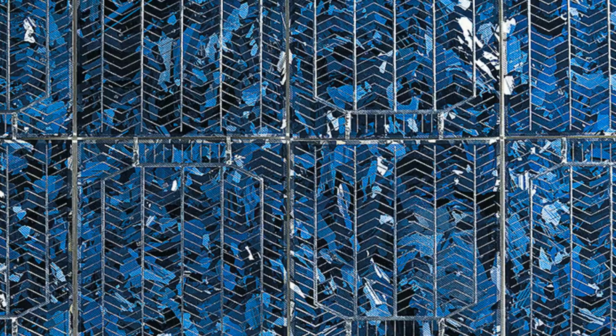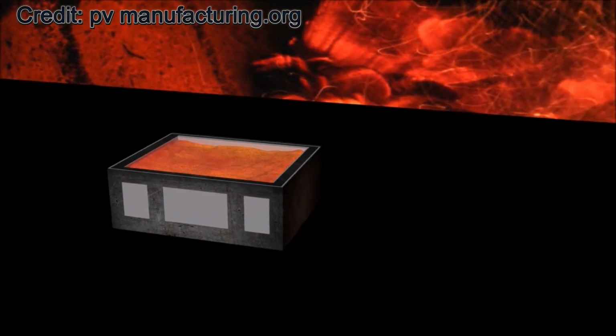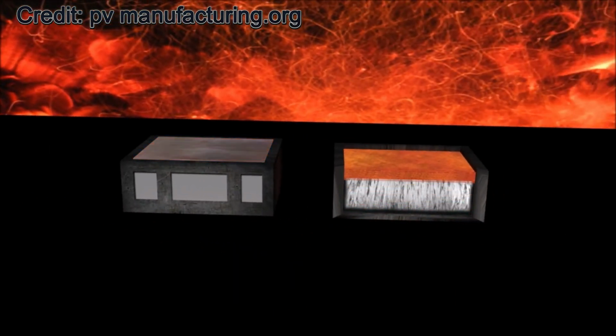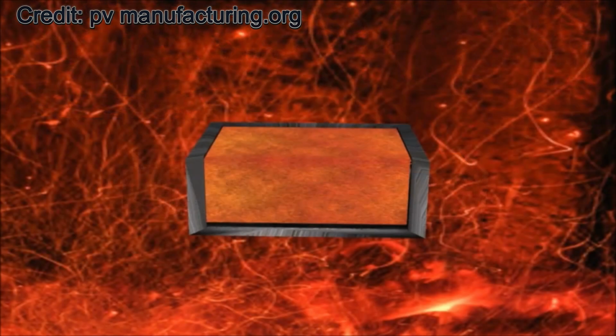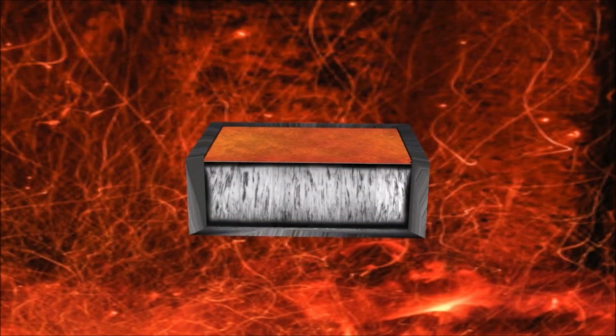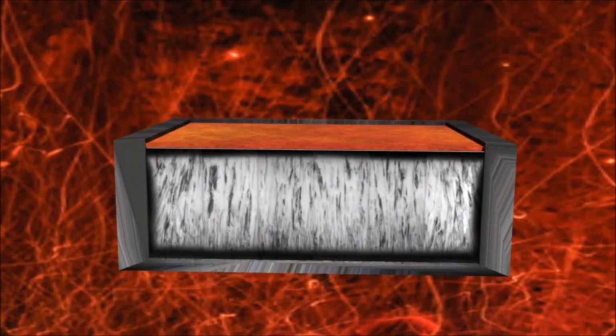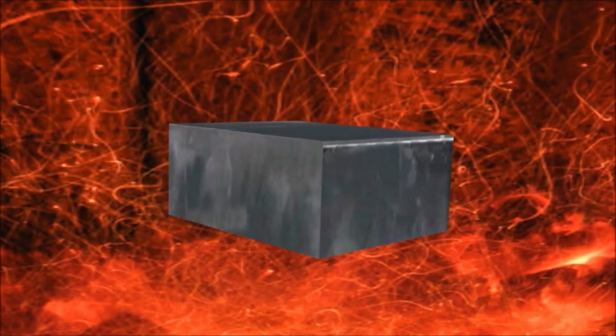Here, manufacturers must choose between two different crystal structures. The first is polycrystalline silicon. This is a cheaper and simpler process where molten silicon is cooled directly inside molds. The result is a material composed of multiple crystal grains, oriented in different directions. As you can see, this method is cheaper and requires less energy and process control, but it produces a silicon with a lower efficiency. The second option is monocrystalline silicon.